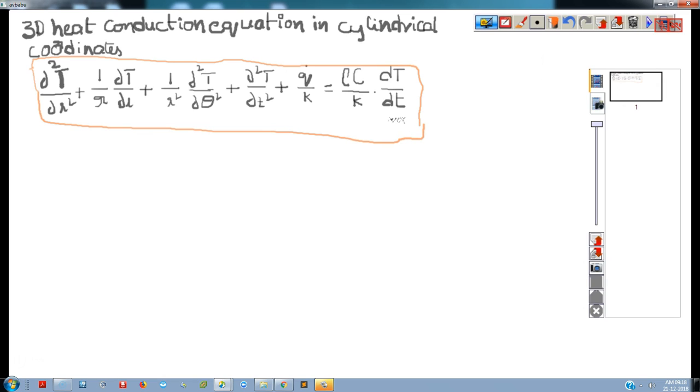Okay, when it is asked to you, when there is a steady state heat transfer, means what? There is no change in the system, in the element, with respect to time. The change in temperature with respect to time is 0, negligible, then this term is also going to be 0, and if heat generation is available, then this equation we call Poisson's equation, right?